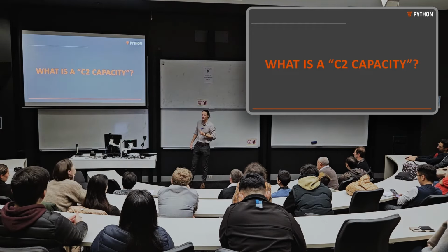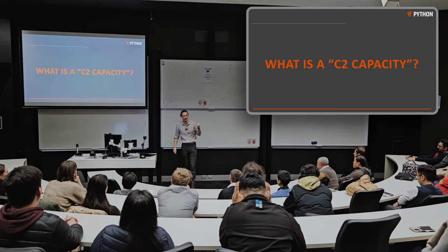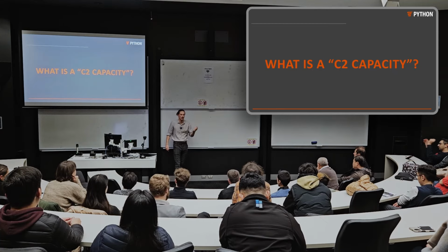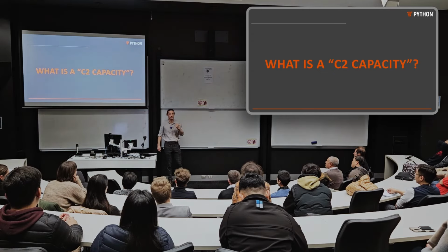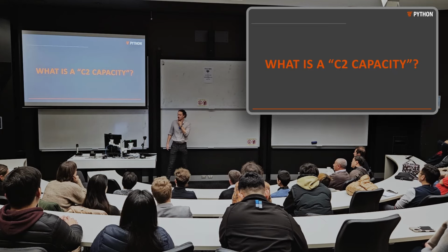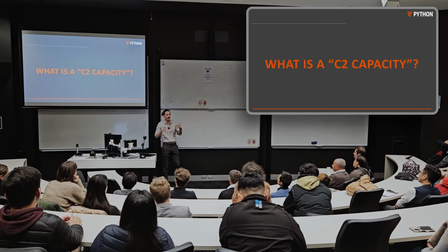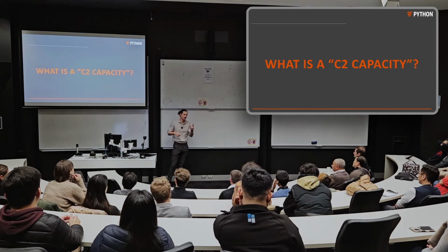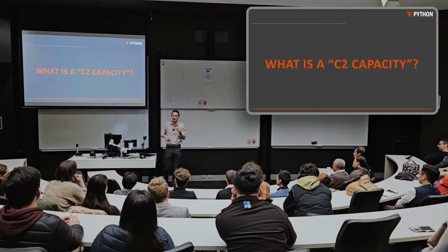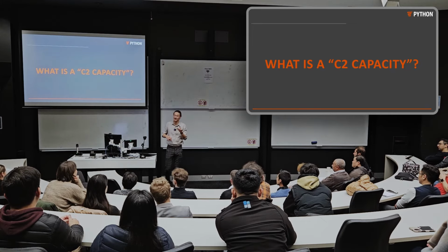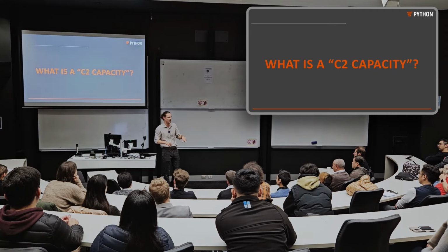If we were to try put a sentence to what we're actually talking about when you look at what a C2 capacity is, a reasonably, sufficiently specific response would be something along the lines of an expected 5th percentile capacity of a post-installed anchor in a reinforced concrete beam outside of the plastic hinge zone in a crack 0.8 mils wide in a 90th percentile, 475-year return period earthquake in Los Angeles, California, America.